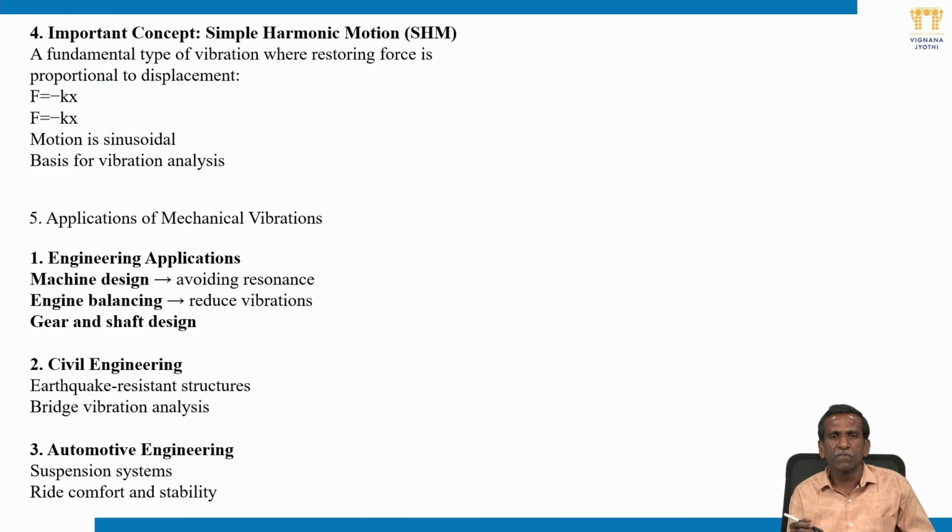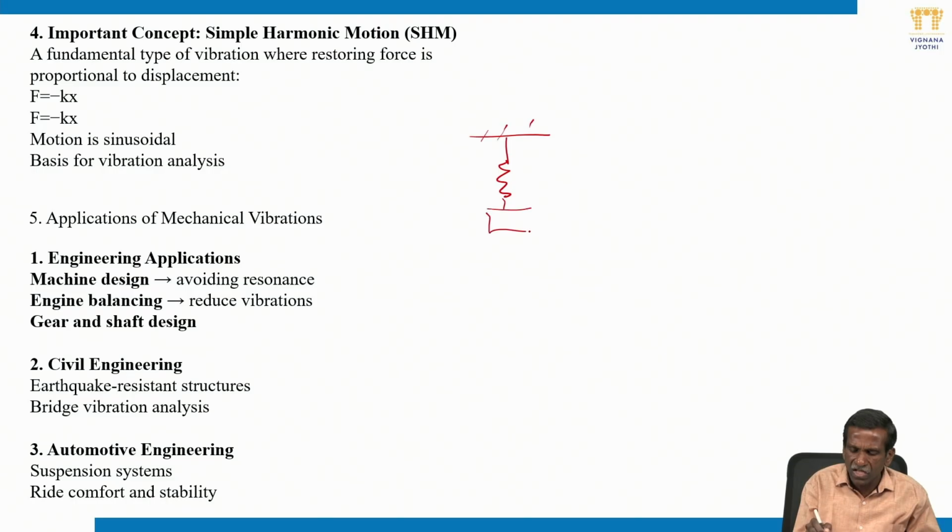We have seen simple harmonic motion, because a pendulum has oscillatory motion. Now if you take the same model I just described, a spring with a mass attached, there is a static deflection, which we have already seen. The static deflection times the stiffness of the spring is equal to mg; that is the equilibrium condition. The restoring force and the applied self-weight of the mass together keep it in its mean position.